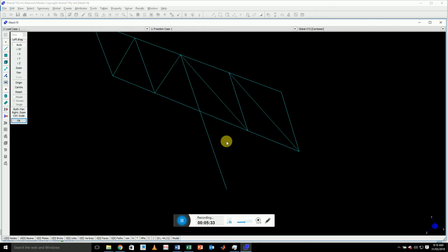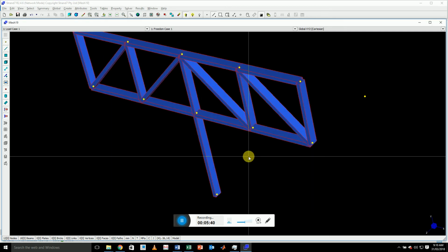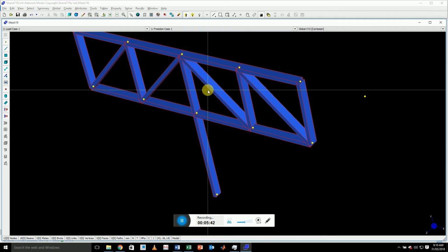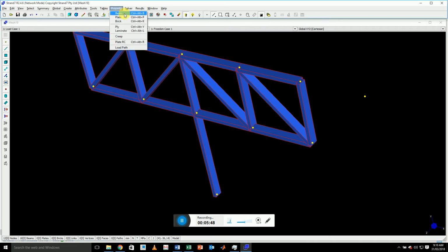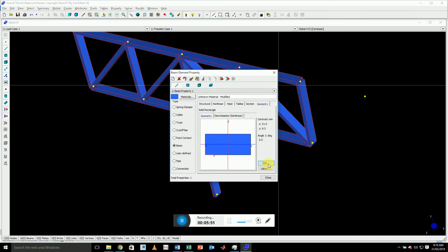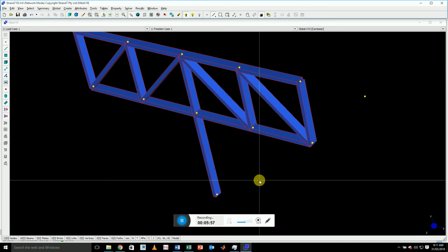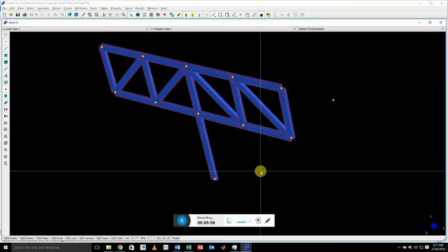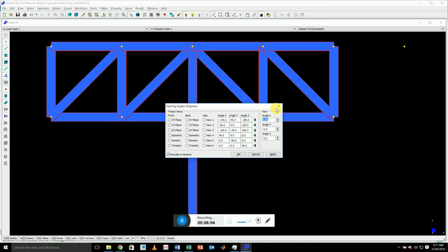If I rotate by hitting F4, or you can press the middle mouse button to open this new window up, and then left click to move around in space. You'll notice our beams are all lying the other way. You can rotate them around by going back into property of your beam is geometry, edit, 19. F3 again, sweet. I want to get square on again, so I'm going to hit F12, XY plane, apply.